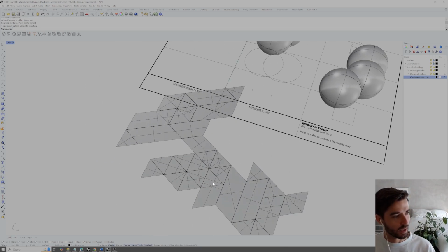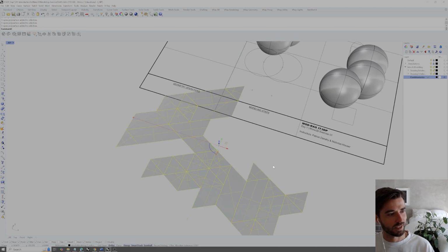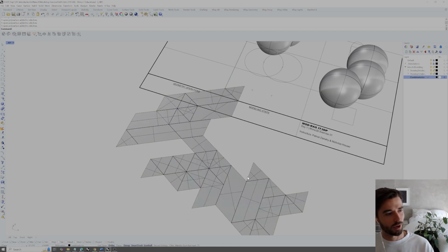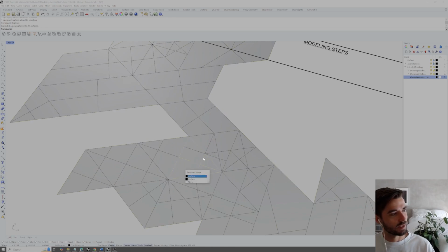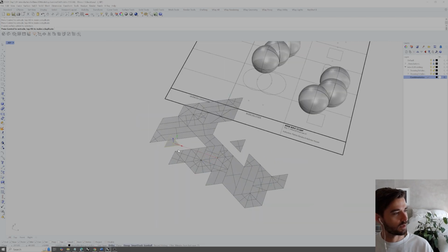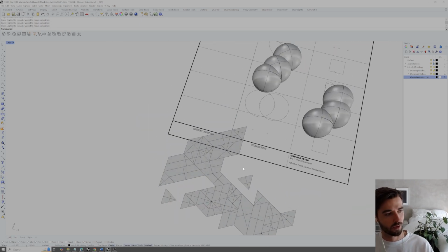And you can see that this makes a really incredibly complicated geometry with a bunch of overlaps. So if we explode this now, we're going to see that actually there's several overlapping faces here. So it's not quite exactly what we need. We would want to move this face out so that we can still fabricate it. We'd have to move this face out, and it starts to get really messy and complex with all of those overlaps.